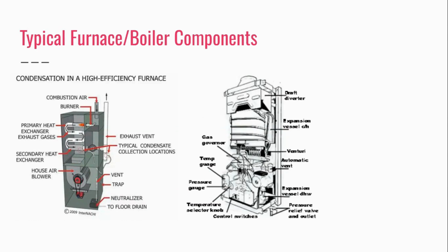So you'll have one that is firing maybe 1 out of 3 times or 1 out of 5 times, or only fires twice out of 10 times. It doesn't matter how it fails. When it fails, it will fail intermittently at first, and then eventually it won't become unstuck. So I will show you guys that in a later slide, but that's typically how gas valves fail.